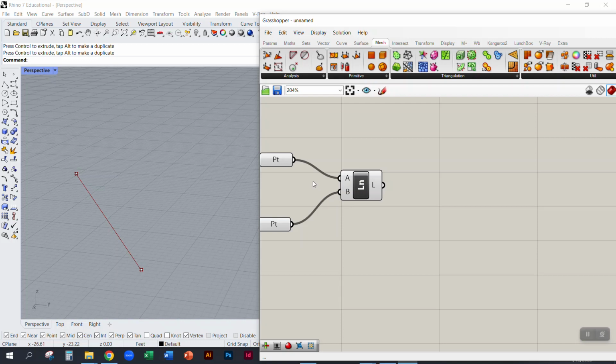Okay, so this can be a workflow that you go in and out from. Maybe you say, okay, I'm going to test some things in Grasshopper, but then once I've reached a point where I'm happy, then I'm just going to go back into manually modeling it in Rhino. Or you can take the approach, if you're more advanced, to design the entire geometry to be fully parametric. So the height of the building can be a parameter, the number of stories can be a parameter, the width. All of these are parameters that you can add in Grasshopper, basically making your own custom command in Grasshopper that you can then design into your own workflow.